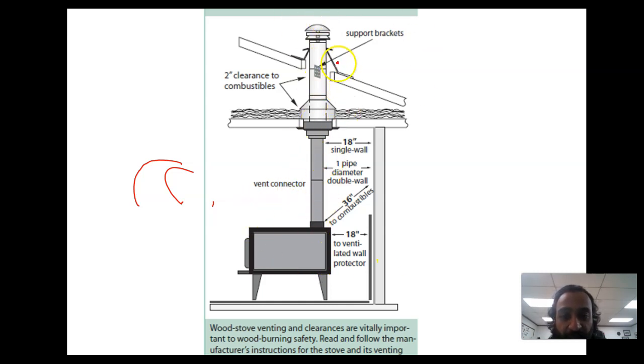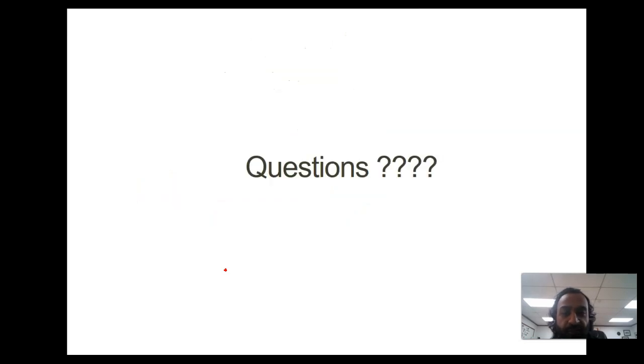And these pipes actually can be used to emit heat. So we are combusting the air, and we're heating the pipe at the same time. You can use this pipe to heat one or two stories as we go along. But you notice in this area here that this pipe gets really hot. So whenever it's going through the ceiling, you want to have a lot of insulator supports, so it does not get very hot and ignite those combustibles. You want to follow the local code before you install to make sure it's not going to hurt anybody or be a fire hazard.